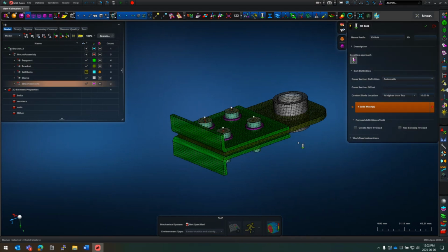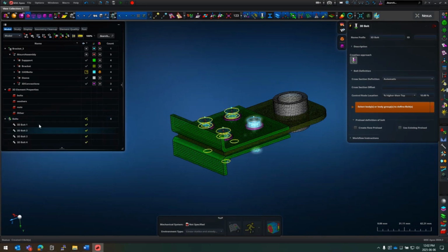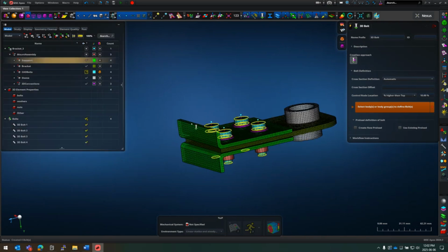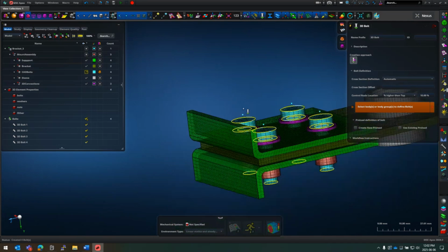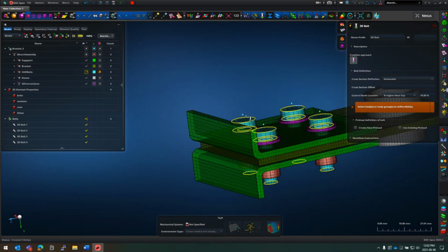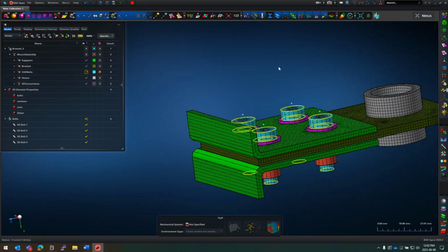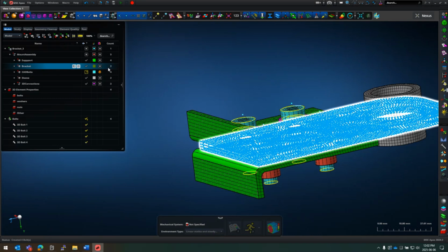What this tool, the bolt method in Nastran, does effectively is figure out what the orientation of the bolt is. I can have bolts in every orientation imaginable; it doesn't really matter. Once I create it, you'll see the bolts, and the bolt entities highlighted. There's an interesting one that appeared there. These little nodes that it added are, if I look at this control node location, 10% outside of the bolt. These nodes are where we'll apply the preload to the bolt and then lock the bolt. In other words, effectively the number of turns that we have applied to the nut, we'll lock that in place.